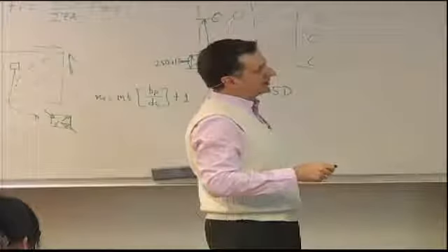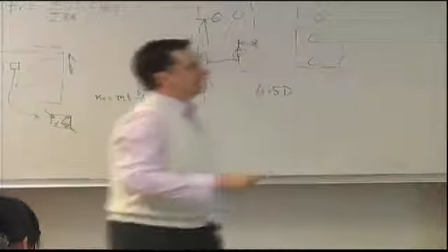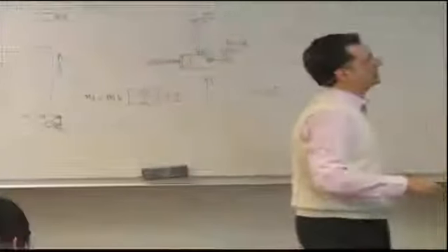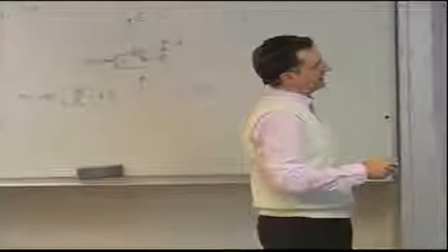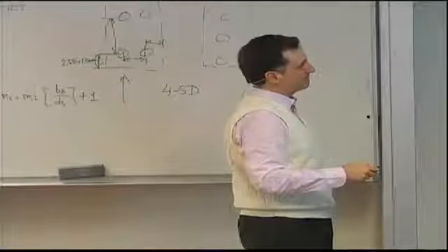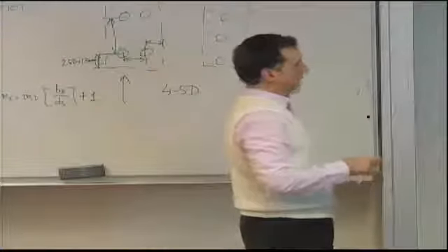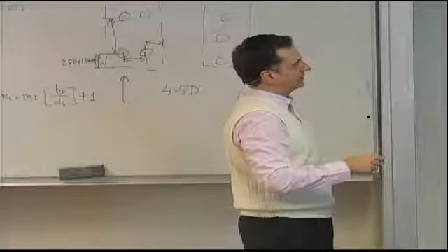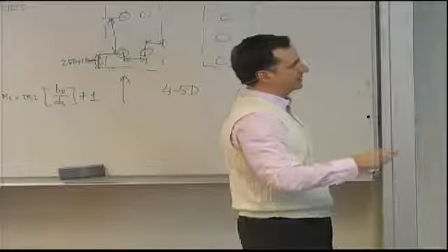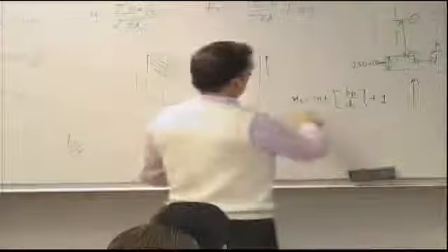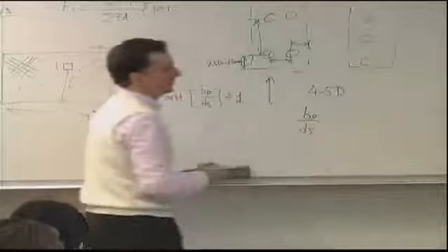And the A for a single stiffener is the EA of that stiffener divided by the full width. So EA of a single stiffener divided by the width of the panel gives us the smeared A matrix contribution for a single stiffener, and multiplied by the number of stiffeners is the term I need to put in there. Now, NS is approximated as BP divided by DS, as we said before.